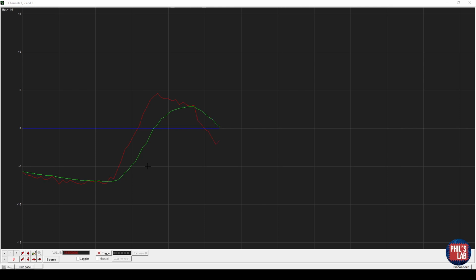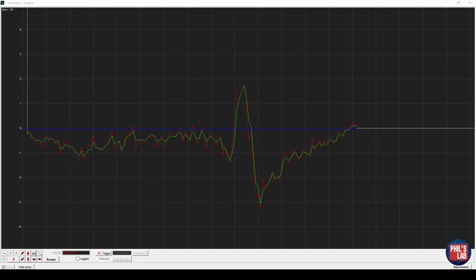So this means we should probably turn down our filter coefficient a bit. Somewhere in the middle, 0.5 is probably a good bet. So this is now with a low pass filter setting of 0.5. You can see again we have much more high frequency noise, but the green trace, the low pass filter trace, does follow the raw data much better.